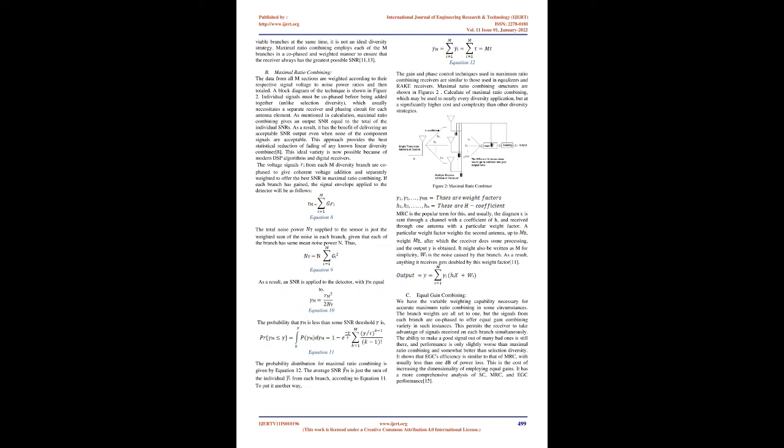When using diversity, it is required to first find the PDF of the fading signal in order to estimate the average SNR of the received signal. To get the average SNR for selection diversity, first compute the derivative of the CDF as a way of finding the PDF, Equation 6. Equation 7 is evaluated to yield the average SNR improvement offered by selection diversity. The mean SNR in the line picked by selection diversity naturally grows, as it is always assured to be over the set threshold, as shown by Equation 8.